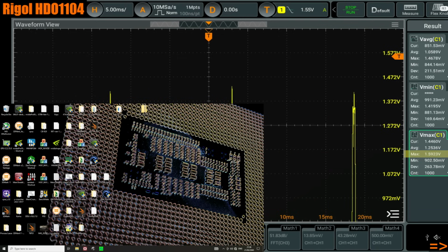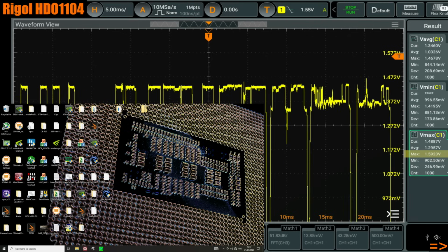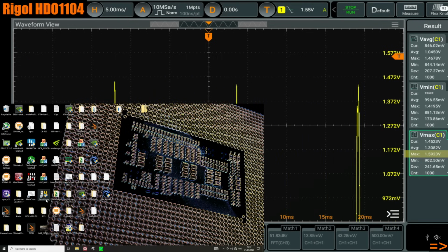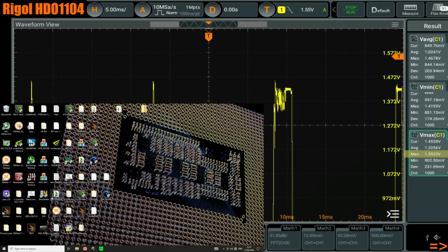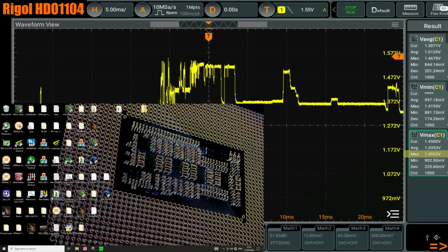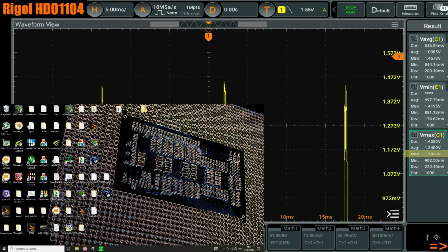Though I've also seen some MSI motherboards that don't work when you remove all vdroop. So, quite frankly, I don't know what they're doing at MSI with their voltage regulator tuning. The number of times I've seen weird bugs on MSI VRMs is just kind of typical. It usually happens at one of the extremes of the load line calibration settings or with the switching frequency settings, where if you max out the switching frequency, things get weird. Or actually, I've seen weird things like changing the switching frequency changing the average output voltage, which is not supposed to happen.